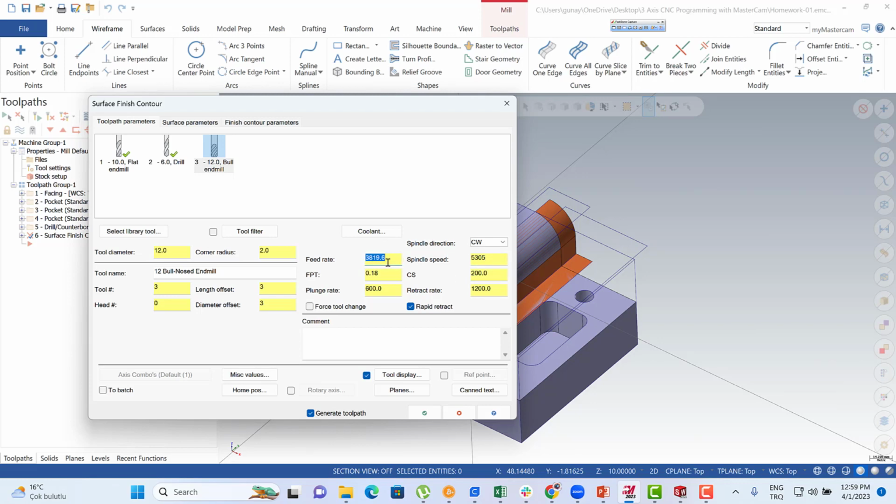are going to be better than the previous one, but we're going to see the tool wear here, okay, is not good for us. And when we consider the tool wear, okay, when you use the 200 cutting speed, it means that we're going to see more tool wear after that process.